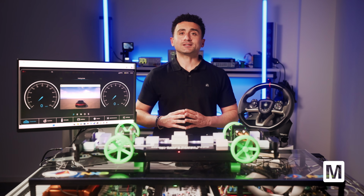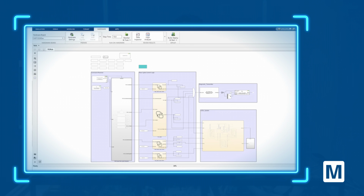CAN communication is managed using MathWorks Vehicle Network Toolbox. The message database is defined in a standard DBC file, and the toolbox handles the decoding and passing of those signals directly into the NXP blocks that interface with the hardware.